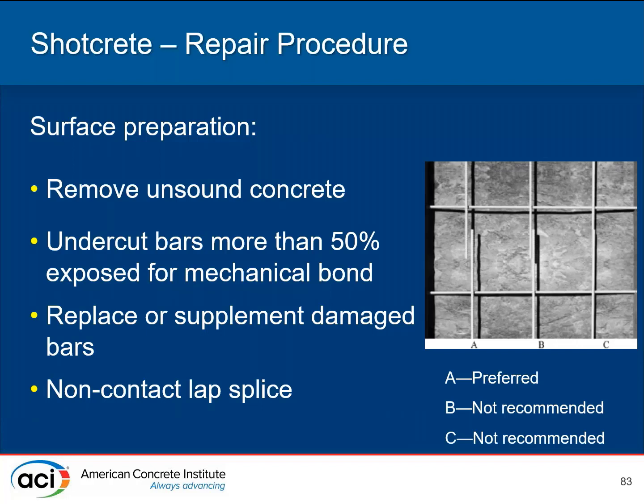The tricky part is, since you're spraying it on and it doesn't flow anywhere, getting behind the bars can be tricky. You can do it from an angle, but it's helpful if there's the opportunity to use a non-contact lap splice instead of a lap splice. You don't have this big area you're trying to get behind.